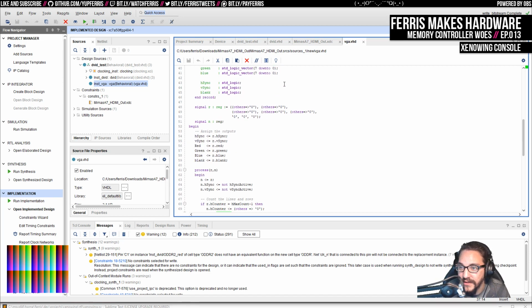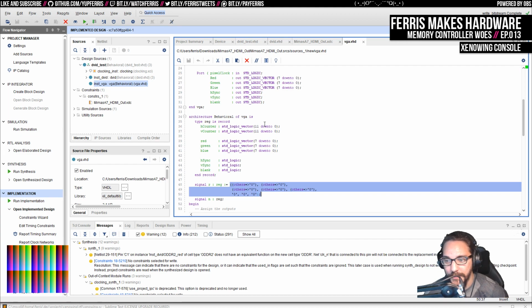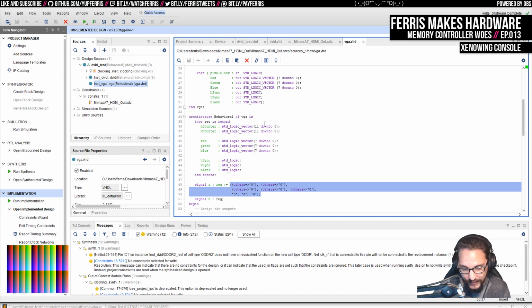So technically, these could start at anything, but I think the initial values are given here. But there's no explicit reset here, which again is probably fine, because on the FPGA, if you just configure, it's going to be what you expect. And then I bet if I bang on the reset button here, it disables the clocks. So that's why you see when I push the button, like now, the signal goes away, but then when I release it, it comes back. And I'm guessing this state just isn't affected because it's not reset.